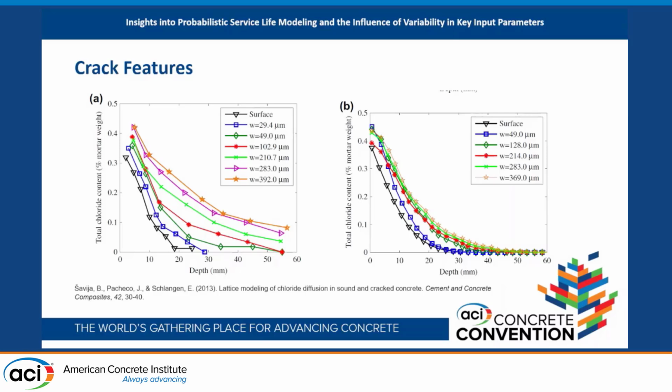I'm going to show some slides because I wanted to emphasize the effect of cracks, and Marwa had one in her presentation that looks very much like this. A lot of people say, well, when you have a crack in your concrete, all the chlorides reach your rebar immediately, and that I don't believe. These are graphs showing that depending on the crack width at the surface, the ingress of the chlorides will be increased for wider cracks, and that's similar to the profile that Marwa showed of a crack specimen.